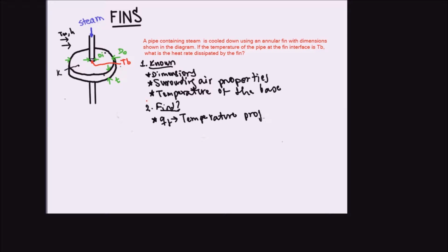Remember, Professor Servio usually says that if you know the temperature profile, you know everything. So usually the temperature profile is to find an expression that tells you what the temperature is in any point of this fin and at any time. And then 3, we're gonna list our assumptions that will help us simplify the problem.